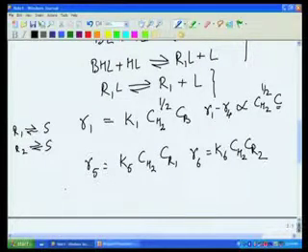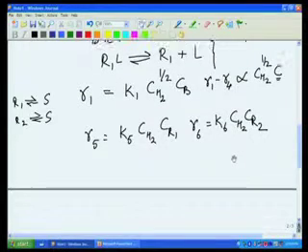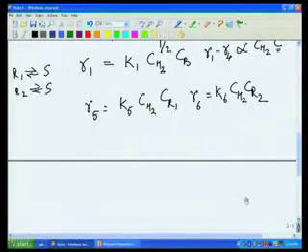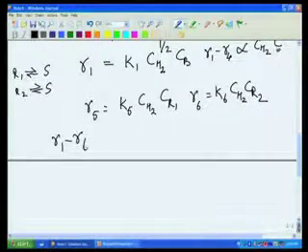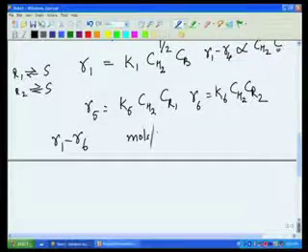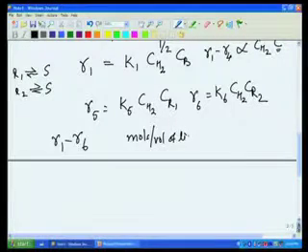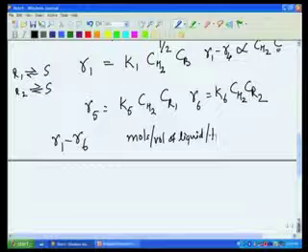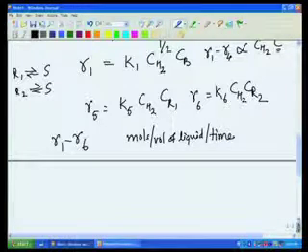Okay. So, we have basically the kinetics of the reaction. Thing to notice here is that R1 to R6 are my intrinsic kinetic rates expressed as moles per unit volume of liquid per time, and Cr1, Cb, Cs, Cr2 are all concentrations of my different species R1, R2, B and so on.